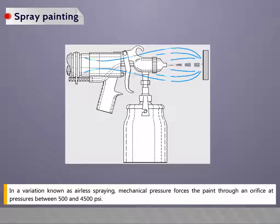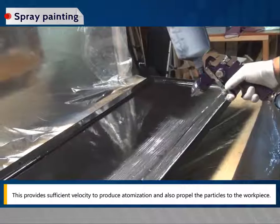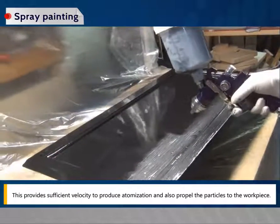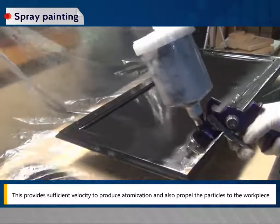In a variation known as airless spraying, mechanical pressure forces the paint through an orifice at pressures between 500 and 4500 psi. This provides sufficient velocity to produce atomization and also propel the particles to the workpiece.